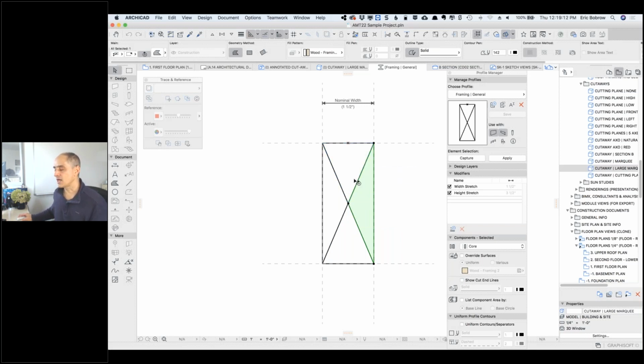Now, ArchiCAD 22, and maybe 1 or 2 years back, it started to be able to say, you know, you could put several of these pieces and it would draw the line for any internal divisions. It used to be that you had to have all 4 of them different, otherwise it would merge them. Now, what I found was you could have all 4 of them the same, but if you put 2 elements side by side or stacked, the line disappeared. I went, oh God, this is painful.